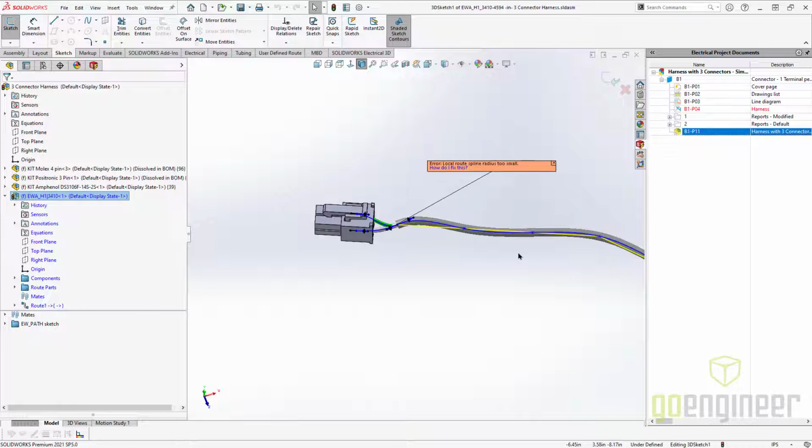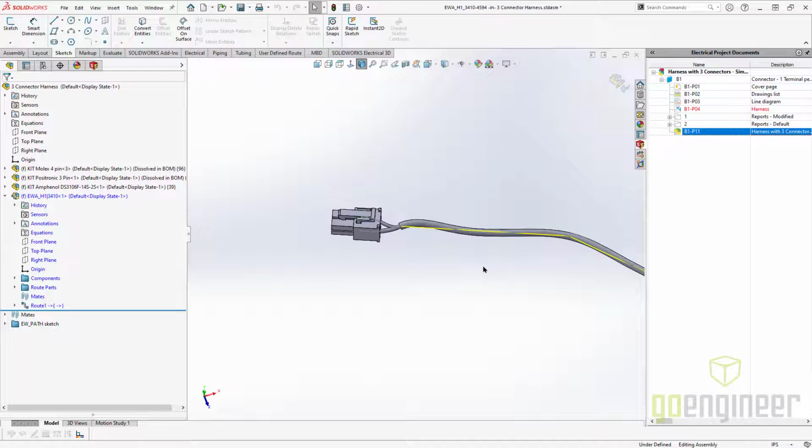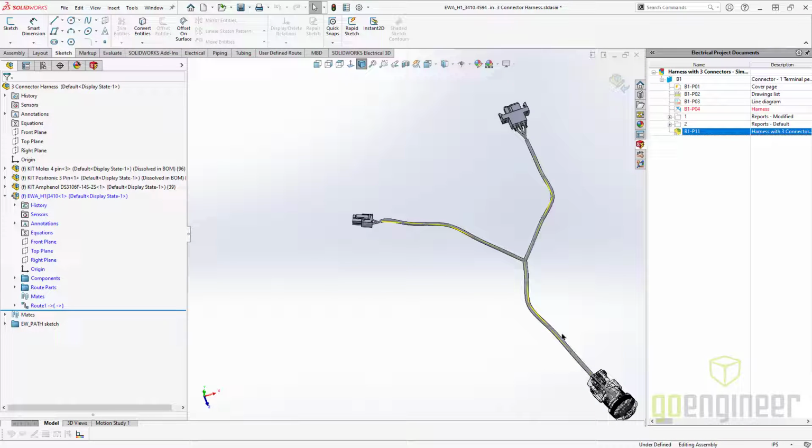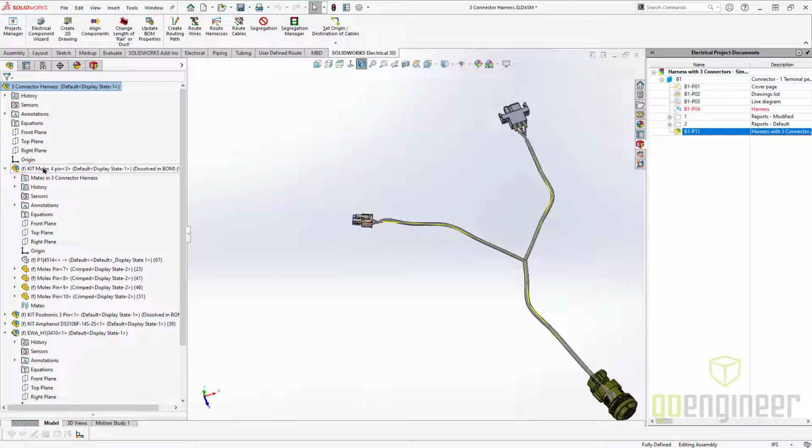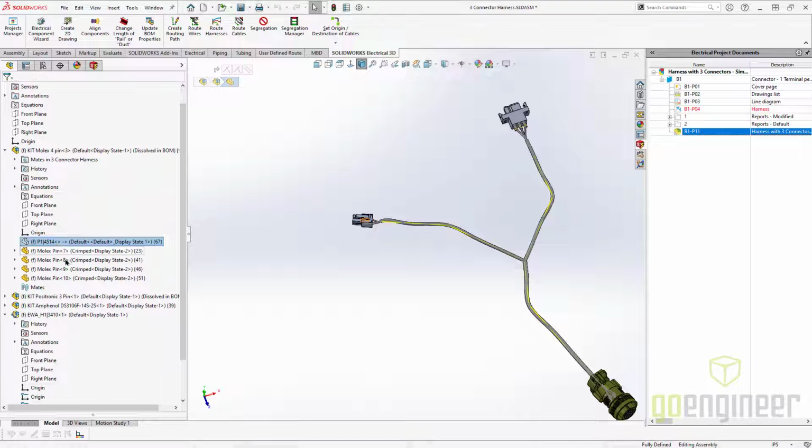But all right, so the other thing to point out with the method that I just used here is because these parts are in subassemblies and I only associated the part, it kind of does a sleight of hand thing. What it does is it takes a copy of the part that you associated, it hides it, which technically removes it from the bill of materials, which normally a hide doesn't do that. A suppress would, but a hide normally doesn't. But in this case it does.